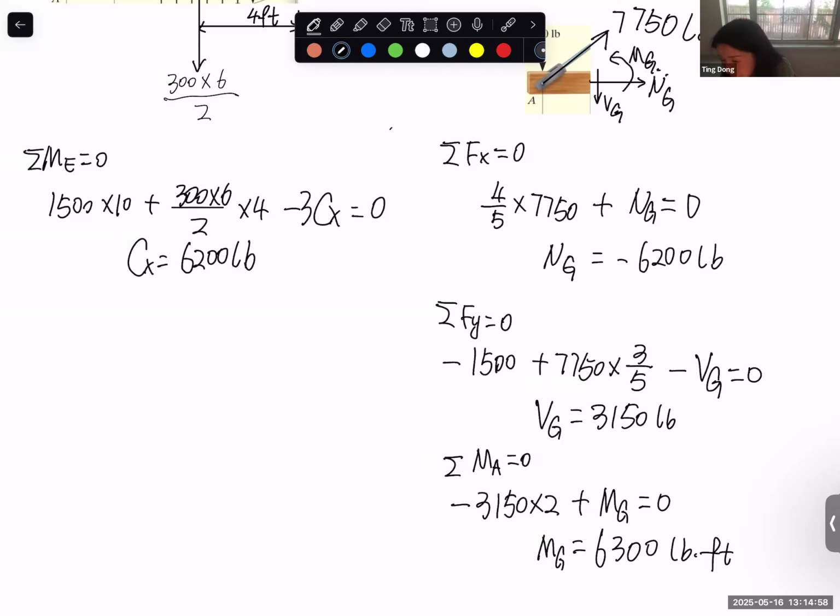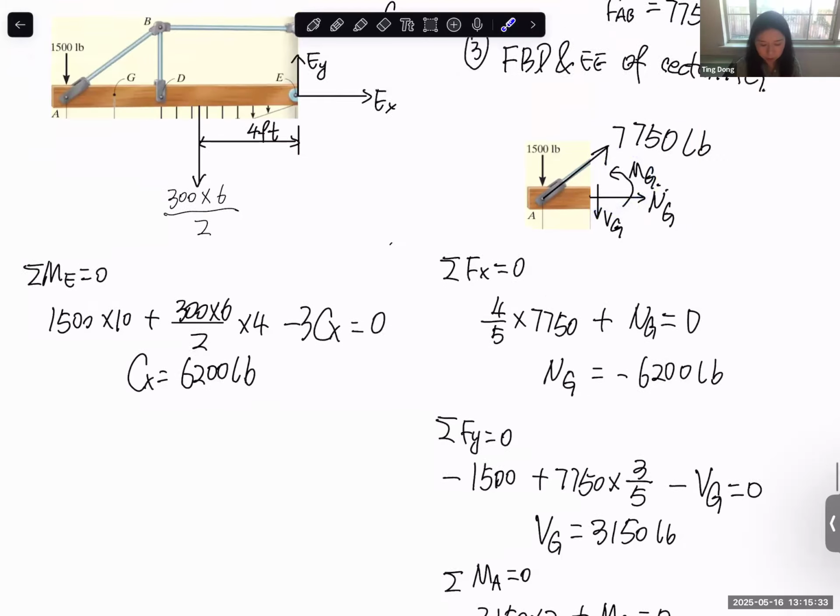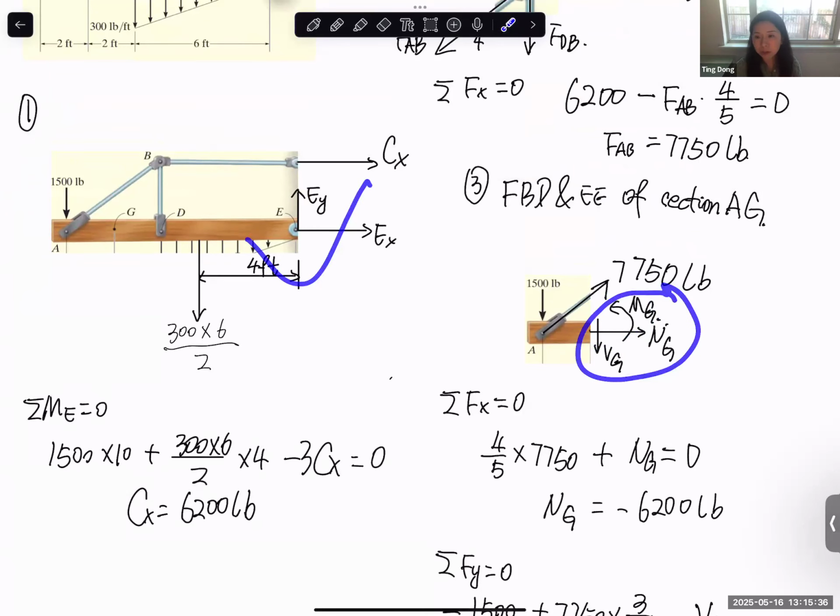When we ask about internal force, you do need to consider normal force, shear force, and bending moment. Whenever we say internal force, it always considers these three: normal force, shear force, and bending moment. But of course, a lot of times some of them calculate to 0. For a simple example, I have a 1D bar with applied tension, and you cut through a certain point of the bar. Only normal force is non-zero. Bending moment is 0. Shear force is 0, right? But when you do the calculation for a general situation, always consider we have 3 components for the internal force.